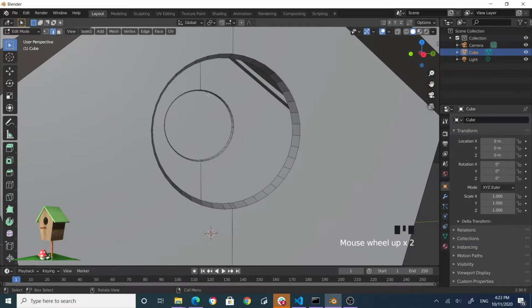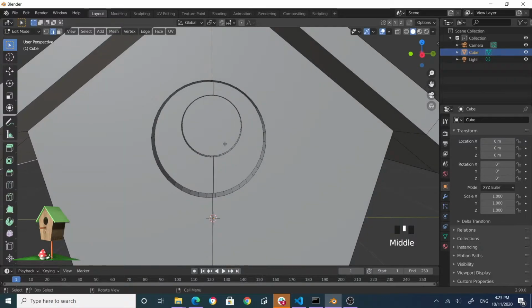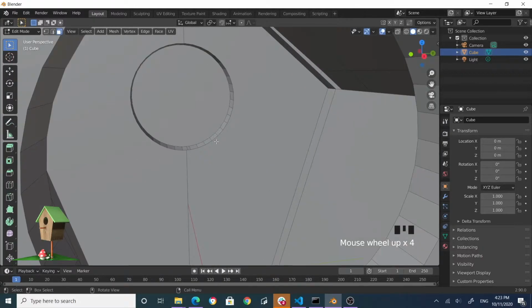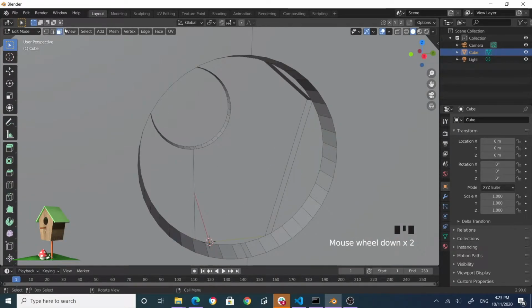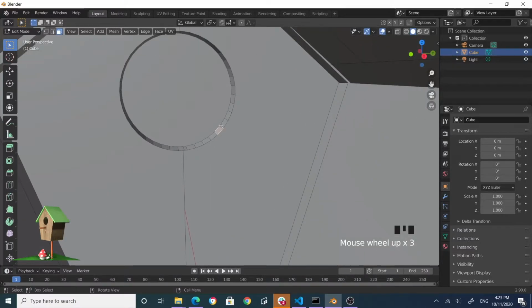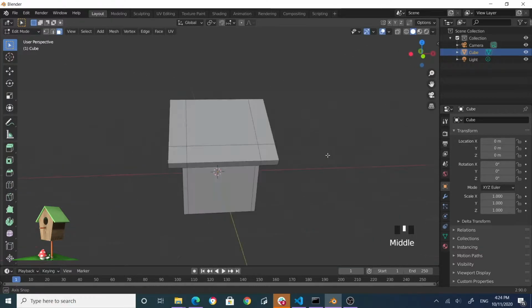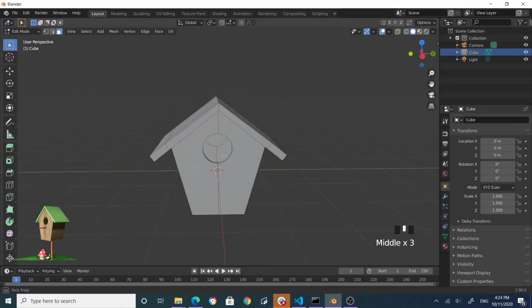Actually these are not necessary, but I can keep it, or if you think that is not necessary, simply select them, come over here and make sure you are in the face selection mode, select the face. If you come across this edge and press and hold Alt and then click, you select the entire face circle, X faces. Now you don't have those extra faces inside.